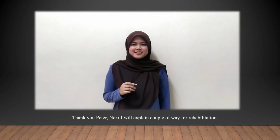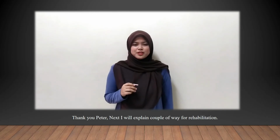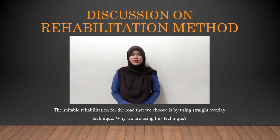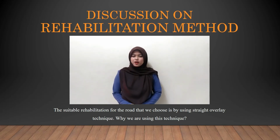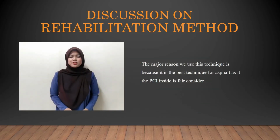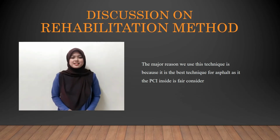Thank you, Peter. Next, I will explain a couple of ways for rehabilitation. The suitable rehabilitation for the road that we choose is by using straight overlay technique. Why are we using this technique? The major reason that we use this technique is because it is the best technique for the asphalt as the PCI inside is considered fair.